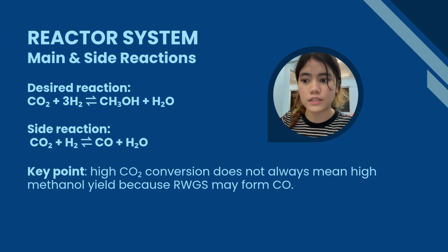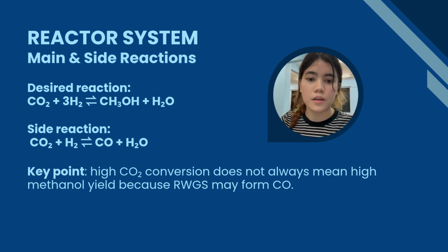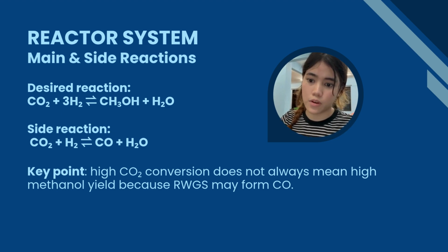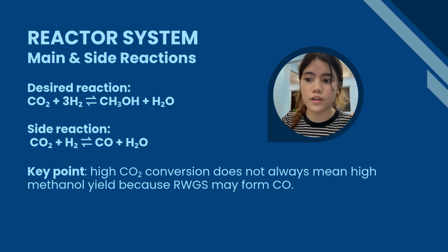In other words, even when carbon dioxide conversion is high, this does not automatically mean that all converted carbon dioxide becomes methanol. Some carbon dioxide can instead form carbon monoxide through RWGS. Therefore, when evaluating reactor performance, we need to consider both conversion and selectivity rather than conversion alone.